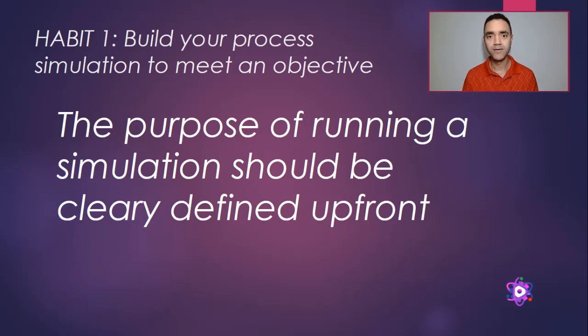For instance, if I want to install a pump in the field and I will use the process simulator to help me with the design of the pump, I need to know the fluid, the discharge pressure, and the inlet conditions of the pump, because without that I will not be able to perform or converge my process simulation.